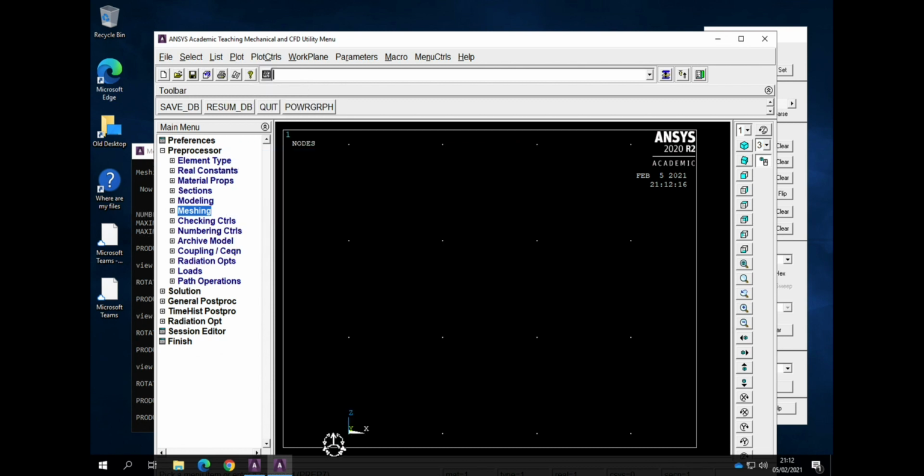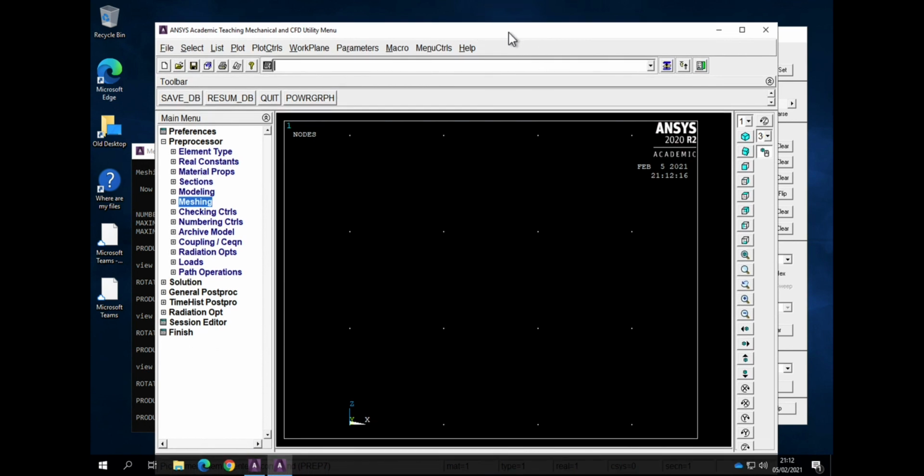You can see now, here's my Z direction. Remember that the way I put the matrix in, the stiffness, piezoelectric and permittivity matrices, is that the active direction is the Z direction, the 3 direction. So what I want is an electrode on the top, all along the nodes along here, and electrodes all along the bottom. I've plotted the nodes, and I want to select entities, and basically make all the nodes at the top at the same voltage.